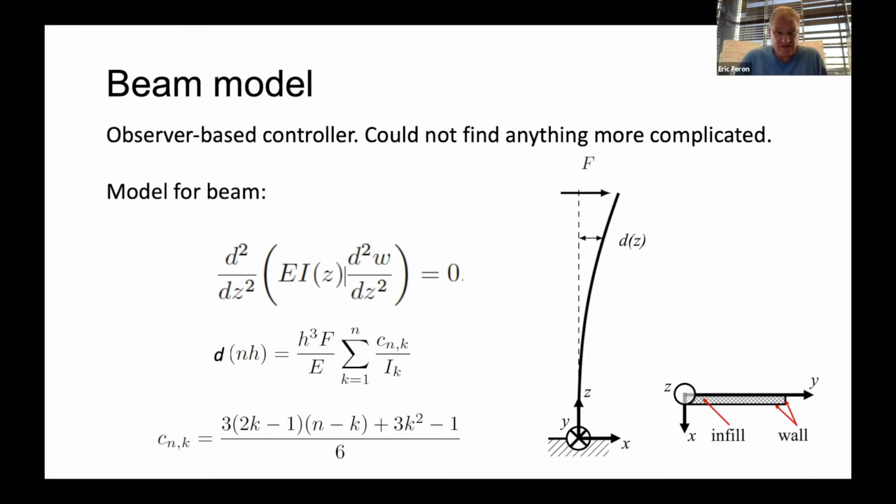With this kind of formulation and this kind of manufacturing, we use the standard Young's modulus and beam moment of inertia parameters in order to obtain the beam shape given the boundary conditions, which include the fact that the beam is cantilevered on the one hand, and that the tip of the beam to which the force is applied is free on the other hand.